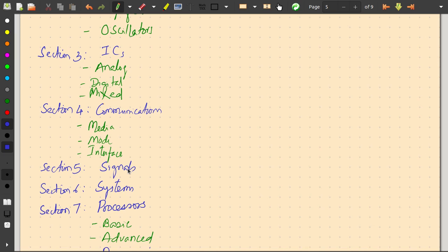This looks like a step input, and when you switch on the system, you get some output, and that output can correlate with the signals we got in the previous section. So just try to find what signal you are getting, and then you say that this is the signal you get from the system when a step input is applied. This is what we call the step response of a system.